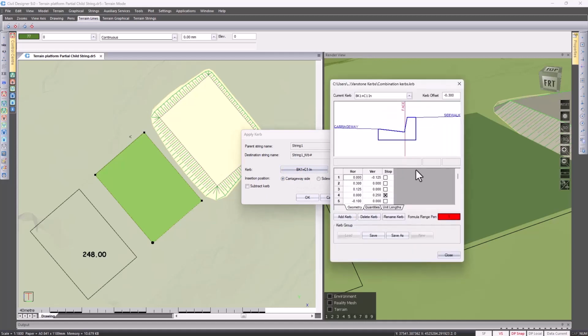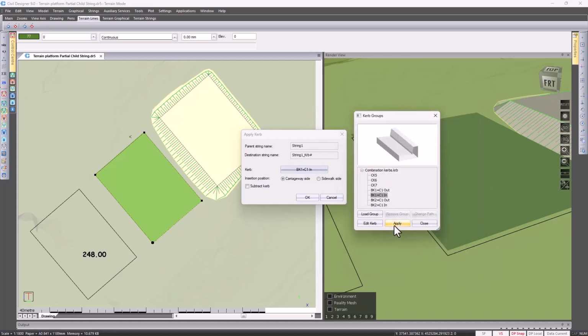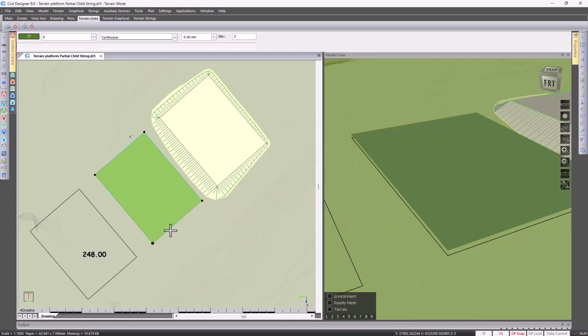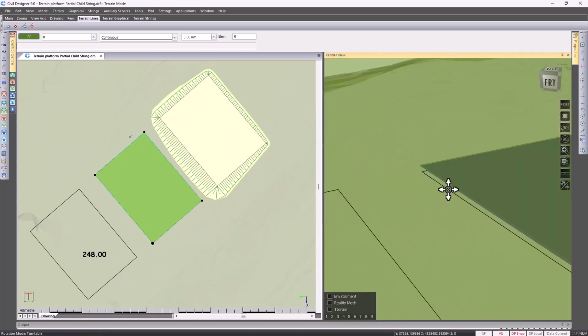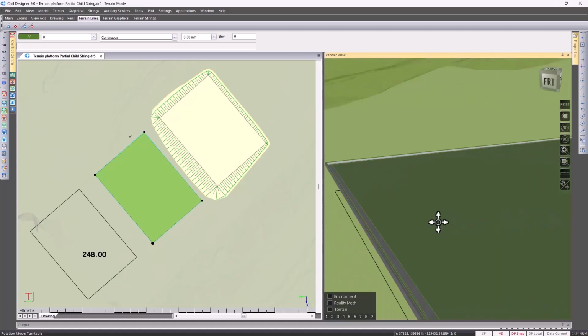If I go to edit curb, so the carriageway side as defined in this curb definition, and then towards the sidewalk. So we're starting here, carriageway, and it's going back towards the sidewalk side. The alternative option is to start the curb from the sidewalk going in towards the carriageway. Okay, so applying that, and then okay, and then just refreshing. So let's have a look at our curb. That curb at the moment running all the way around my platform.